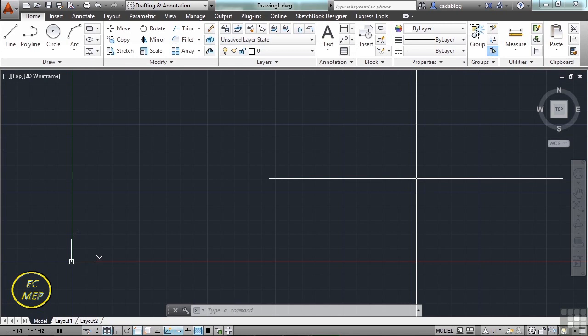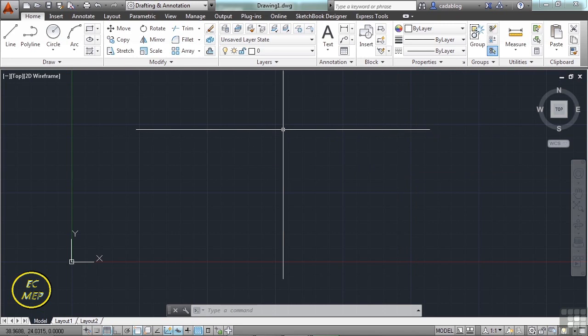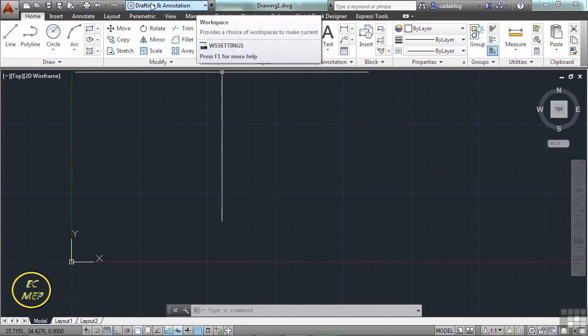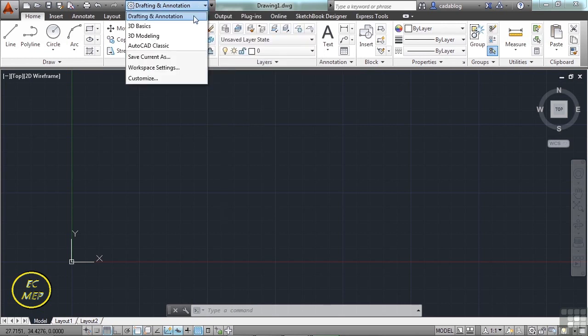If you want to get to the toolbars and the menu bar, AutoCAD has a workspace called AutoCAD Classic. Turn it on by switching workspaces. Well, your workspace is your user interface screen in AutoCAD. It can be arranged in many different ways for any reason you want to. AutoCAD has 4 main workspaces right out of the box. You can change them up here in your quick access toolbar. Click on the arrow and select the one you want.